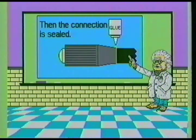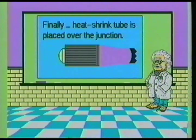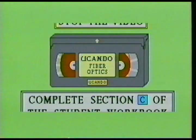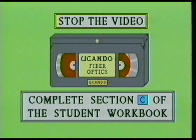Next, the metal part of the connector body is crimped or glued to the protective coating around the fiber core. Finally, heat shrink tube is used to seal the cable connector junction. This reduces the chance of contaminants entering the connector. The three most common types of ferrule finishes are flat, domed, and protruding fiber. This concludes review number 3. At this time, you should stop the video and complete section C in your student workbook.